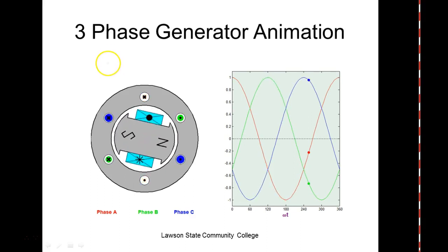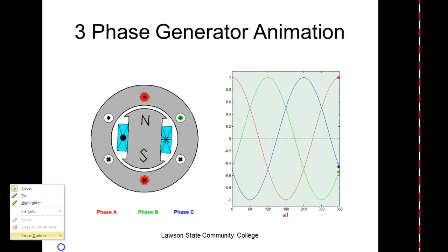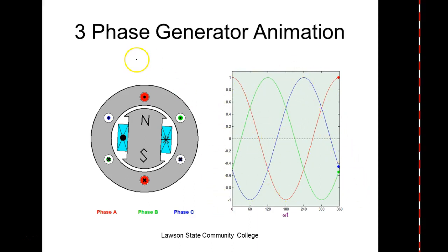And basically, this changes all our power formulas when we start dealing with 3-phase. What happens is the phases are spread out. The current is vectored between these 3 phases. Well, we can't really say leading or lagging in this situation, because if we call one of them A, which would be this one, we could say that one lags by 120 electrical degrees.